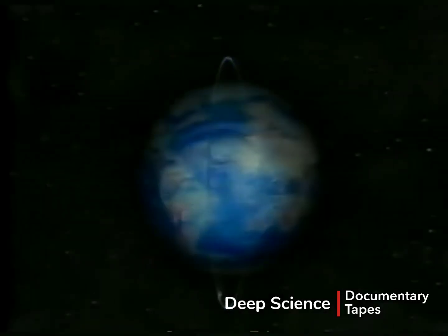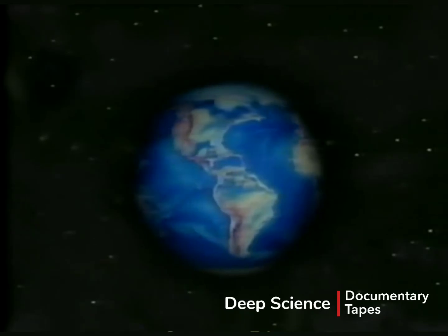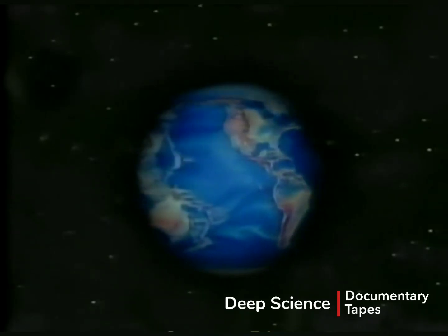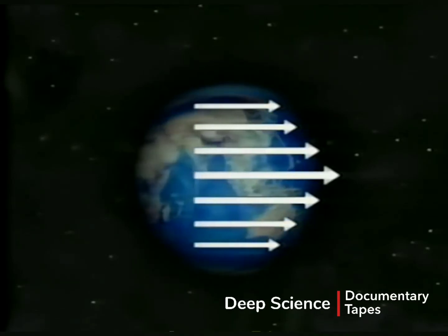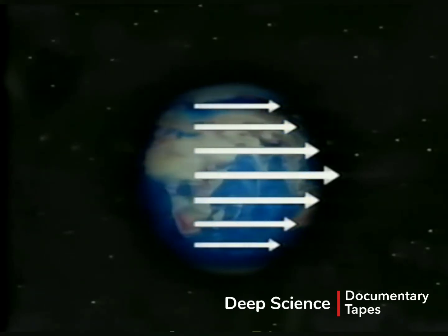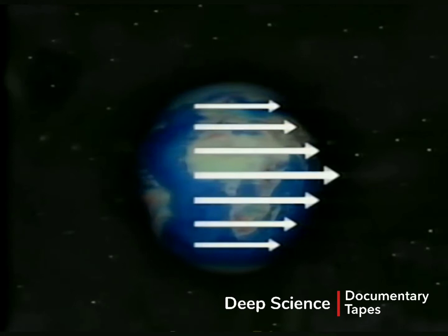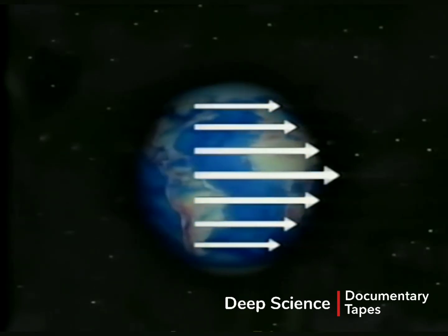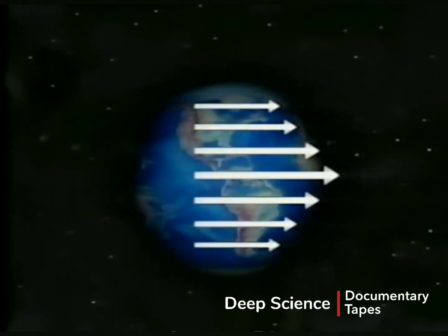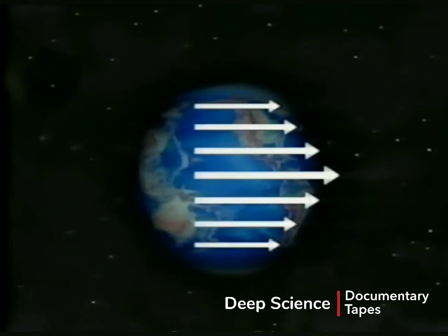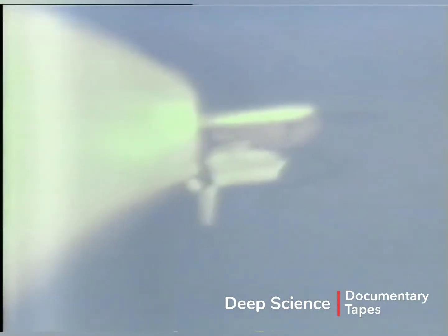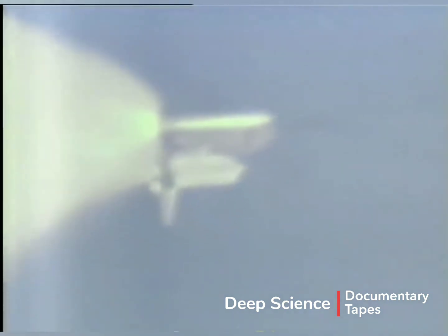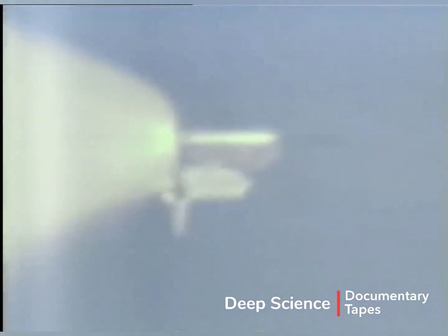The Earth is constantly turning, and all points on its surface have an eastward velocity, with the greatest velocity occurring at the equator. The farther the launch site is from the equator, or as launch azimuth is increased or decreased from due east, less of the Earth's rotational velocity will be imparted to the launch vehicle. This requires more fuel to get into orbit, or payload weight will have to be decreased.